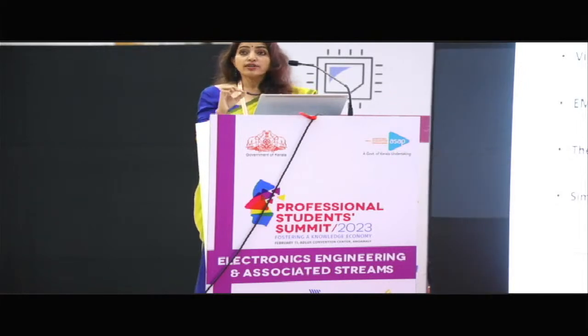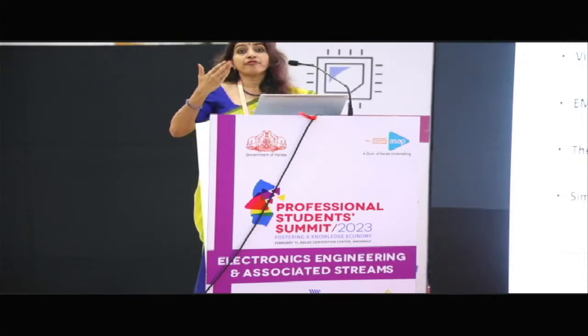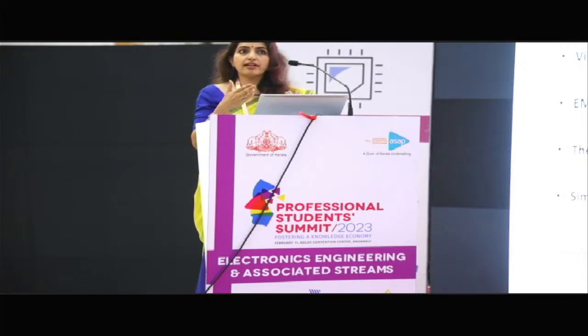So all these packages will be subjected to vibration tests, and there will be two levels. One is a flight level, the normal level, and then it will be subjected to the qualification level, which is 1.5 times more stringent than that. If any component fails in that, then the package will not be allowed to fly, and we will be asked to rework the full design and come back. So that is the vibration test. We have two types of tests, sine vibration and random vibration.